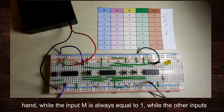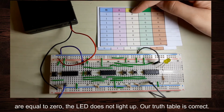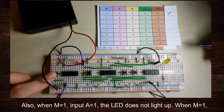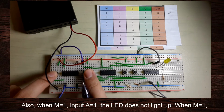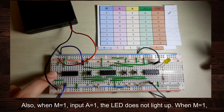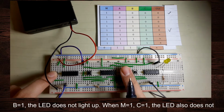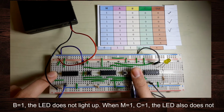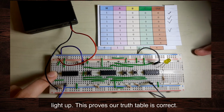On the other hand, when input M equals 1 while the other inputs equal 0, the LED does not light up. Our truth table is correct. Also, when M equals 1 and input A equals 1, the LED does not light up. When M equals 1 and B equals 1, the LED does not light up. When M equals 1 and C equals 1, the LED also does not light up. This proves our truth table is correct.